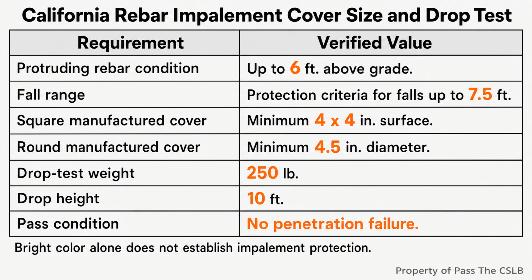All 4 subjects in this lesson point to one management habit. Identify the boundary before production starts. For licensing, the boundary is the contract scope. Is this truly a multi-trade General B project, or is it an isolated specialty contract? For Shotcrete, the boundary is the live placement event. Is the qualified nozzleman ready, and is continuous special inspection present before the work becomes concealed?